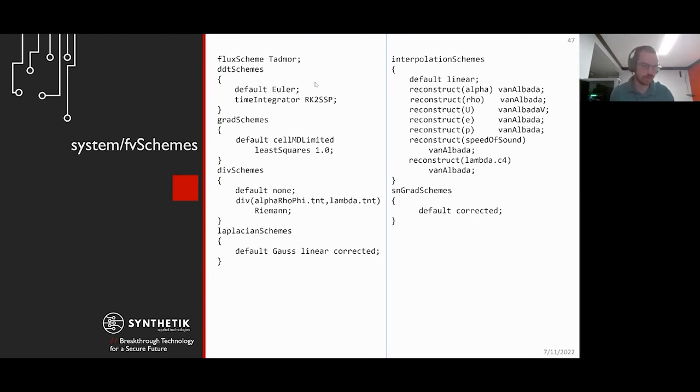So I still don't recommend going above a Courant number of 0.1. But especially for detonation problems or other, I'd say harder problems, you can accidentally go over that 1 for a time step or 2. In some cases, that will cause you to fail almost immediately. However, with the higher order or the higher step variations, it will make that much smoother and you won't fail. At least you're less likely to.